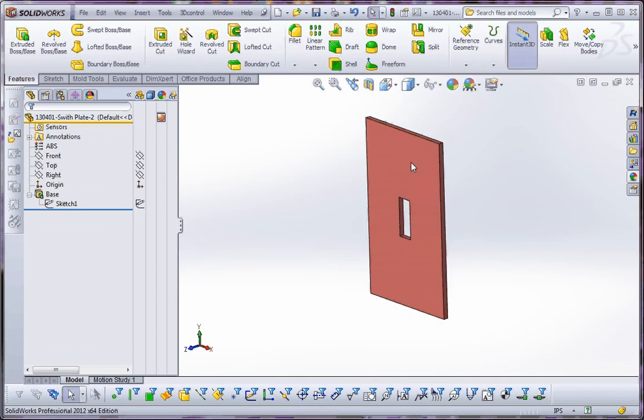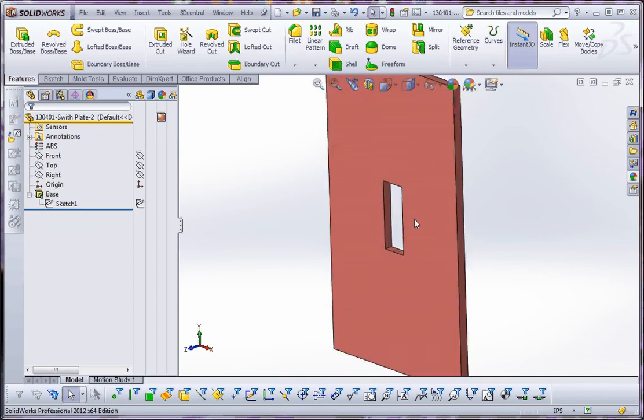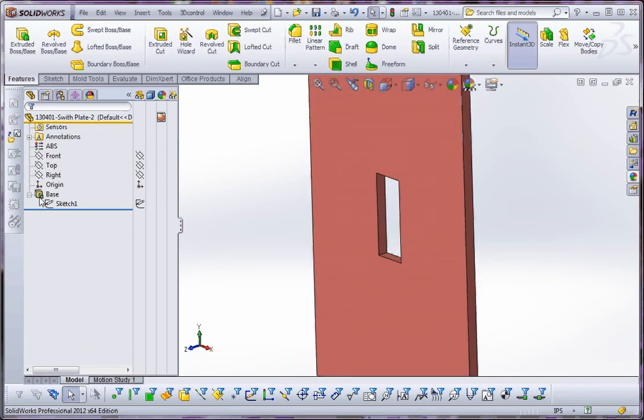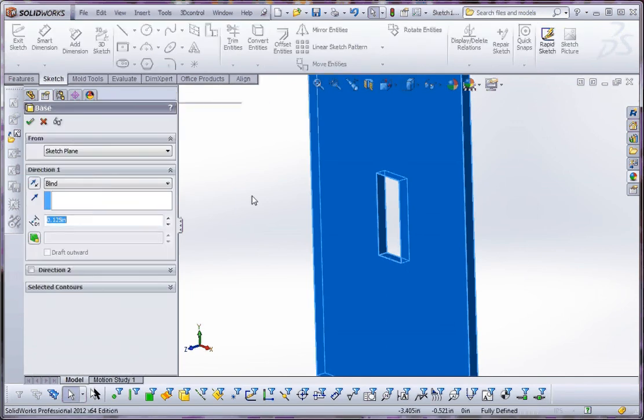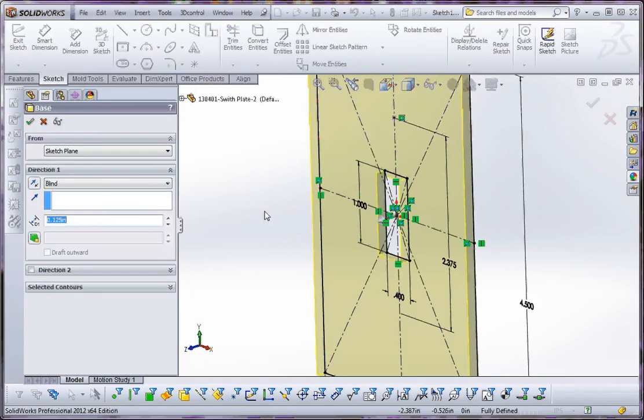You have to select the whole feature and move that around. We can't just select that hole because there's nothing over here, no hole over here to select. So I would suggest doing this. If you plan on doing something with a hole feature or another feature that comes after this, create that as a different feature. The way you would do that is you go to your base feature. It's called base because we renamed that.